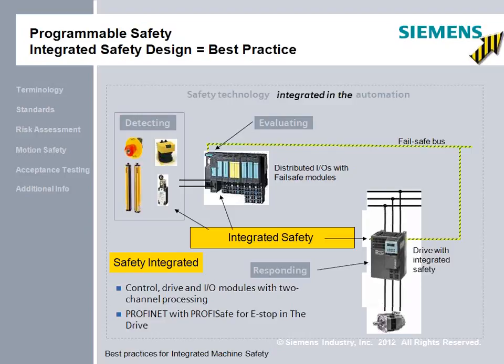What do we gain from this? We typically increase the level of safety, functional safety. We many times increase the flexibility of this implementation so that if we need to refit or modify the implementation as we retool, it typically is much simpler to reprogram a programmable safety controller than it is to rewire and redesign a safety relay system.